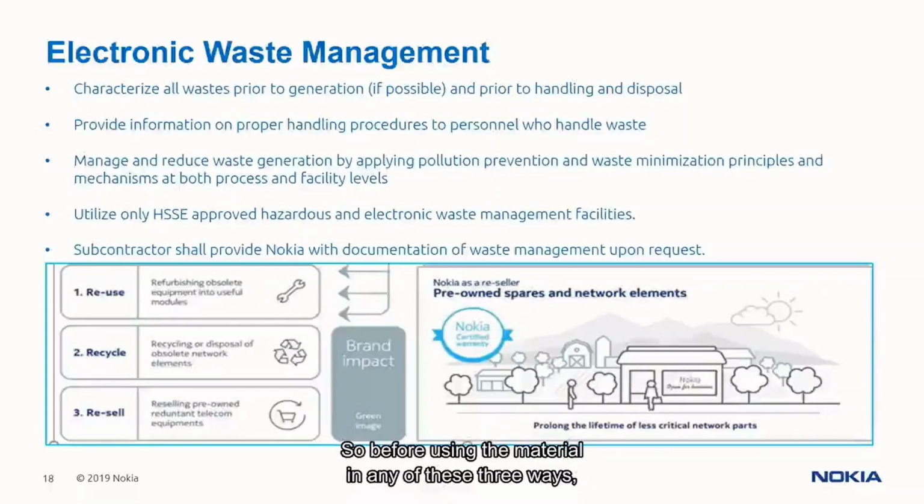So, before using the material in any of these three ways, there are some guidelines which should be followed for waste management. Prior to handling a disposal, if possible, we should characterize all the waste prior to generation. We should provide the proper training and information on handling procedures to the people who handle this waste. We should manage and reduce waste generation by applying pollution prevention and waste minimization rules.